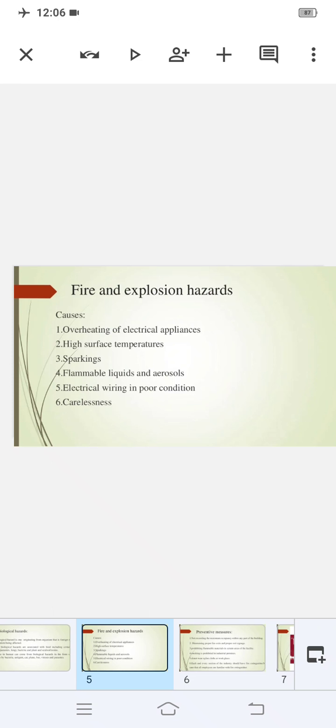Spontaneous combustion and non-explosion proof electrical equipment are potential ignition sources for that. The effect of fire on people takes the form of skin burns due to thermal radiation from the explosion, and the severity of the burns depends on the intensity of the fire and the explosion timing. Fires occur in industry more frequently than explosions and toxic releases, although the consequences in terms of loss of life are generally less.